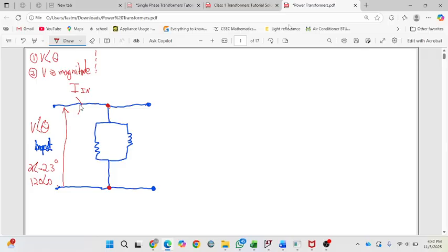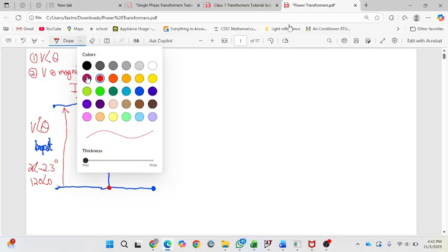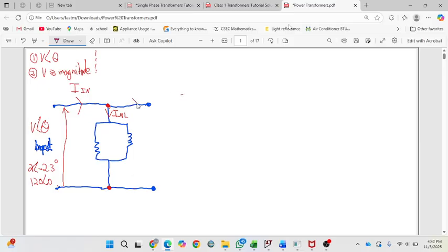As it continues to flow, your input current at this junction splits into two directions. The first is your no load current, which is basically the current when you have no load, which is your open circuit test. And then the other is the current that's actually going into the transformer, or rather, this is already in the transformer. You can think of this purple current as the majority of the current going into the coils itself. The labeling for this is I1, right? You have to understand these labels, because in the exam they will tell you to calculate these things, so you have to know how they relate to each other, right?